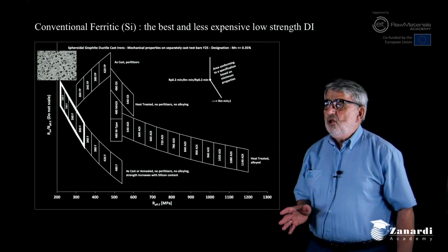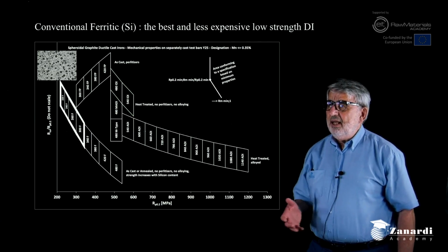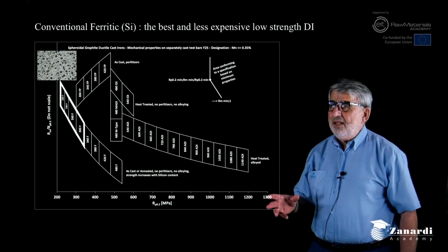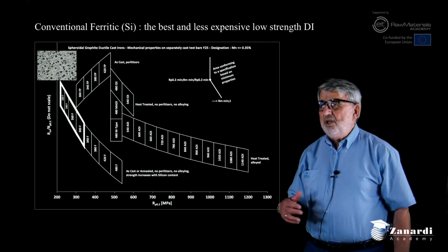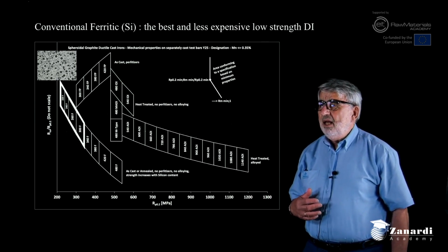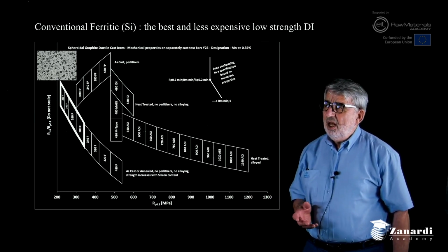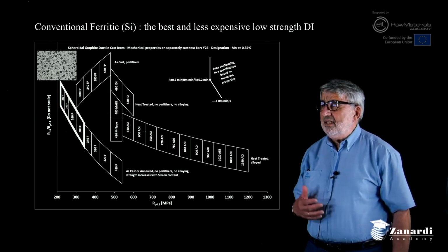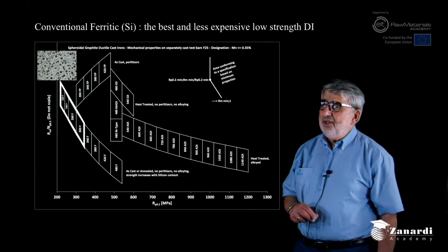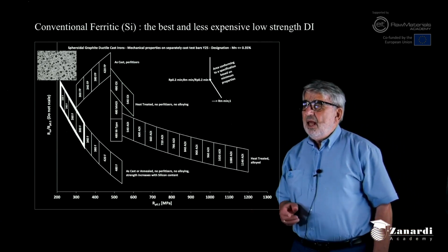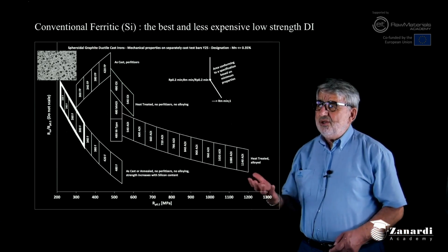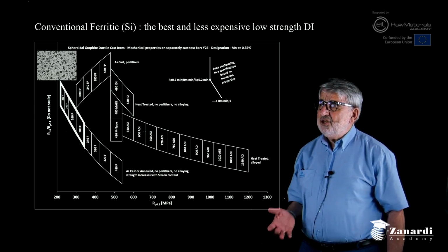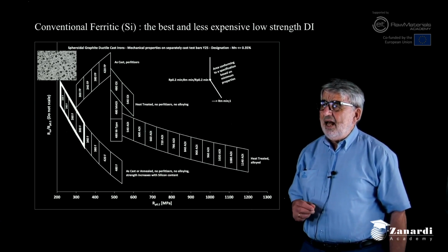This was the normal range of the ferritic grades definition, where the silicon was low for high impact at low temperatures, or at the maximum level of 2.8 to avoid carbides in thinner sections, and so on. And this was the first family, very popular, machinable, with a very controlled hardness range.